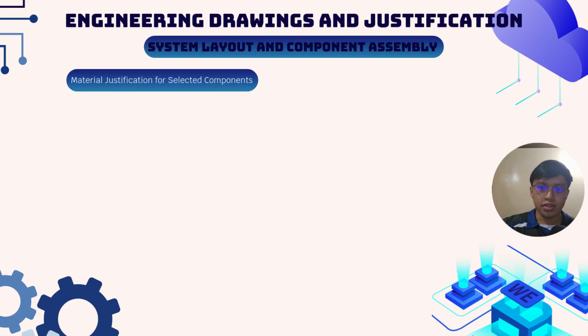These are quenched and tempered to reach 800 megapascal tensile strength, ensuring they maintain their preload clamping force even under heavy machine vibration. The slider bed support plate uses 3 mm ASTM A36 mild steel. It's a cost-effective choice that provides the rigidity needed to support 3 kg trays without sagging.